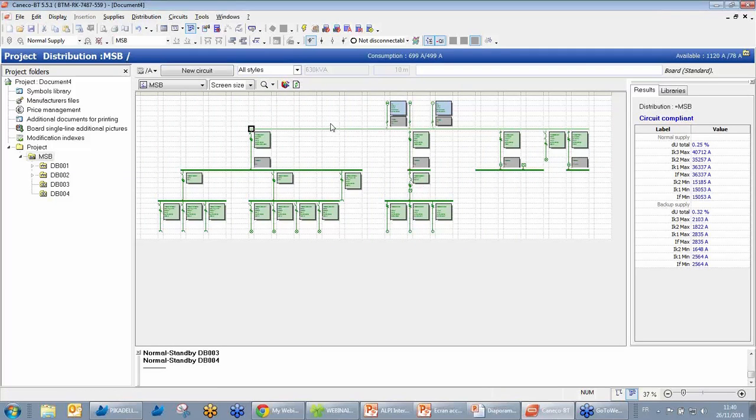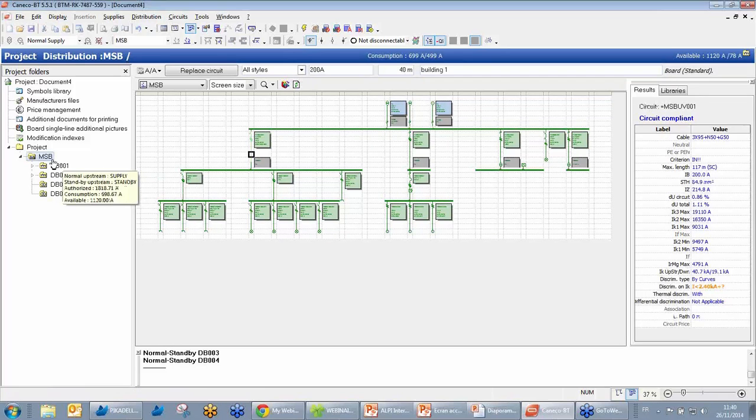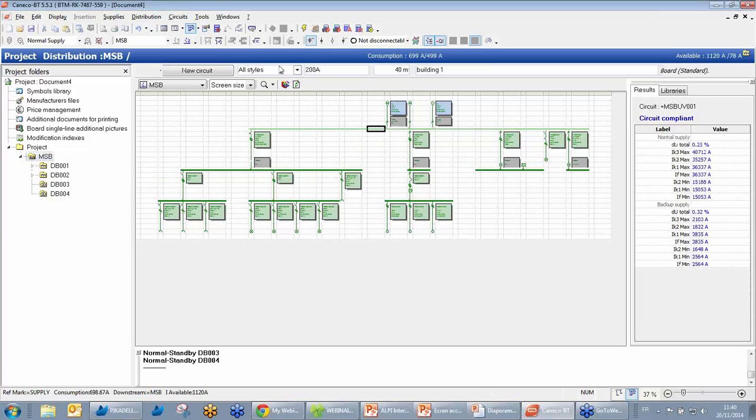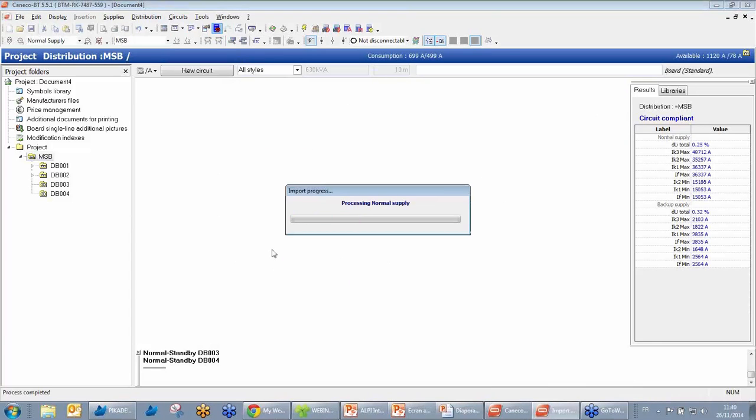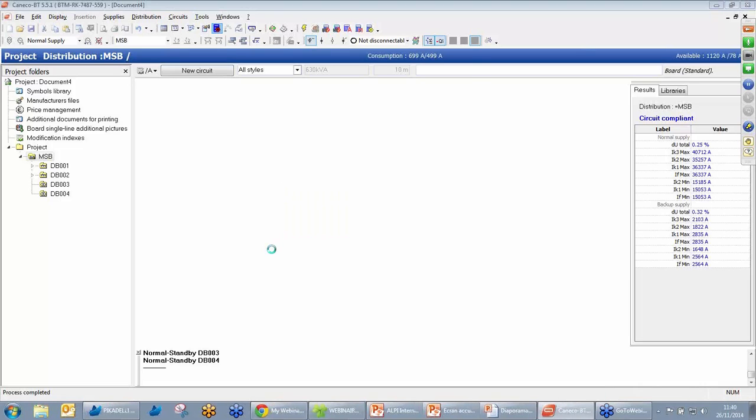Okay, so right now, if I want to get the enclosure of my equipment, I can just click on which distribution board I want to do the automatic enclosure. So I can say that to place here. I check the box, the button cabinet composition. So it will reload all my projects with equipment, with protective devices. And right now it will suggest a window where I can choose which brand and which kind of enclosure I want to use for this cabinet.